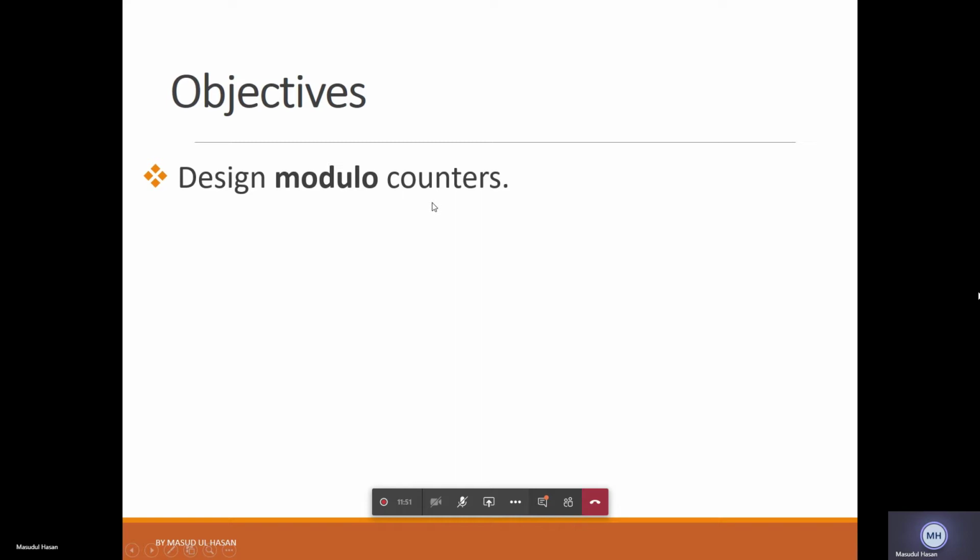This Q2 will be available after some delay due to the propagation delay of this one, and due to the propagation delay of this one, this Q3 will be more delayed. If there is a fourth one, this delay will increase. So this is like a cumulative delay. So what will happen? All of these 3 are out of synchronization. Their timings are different.